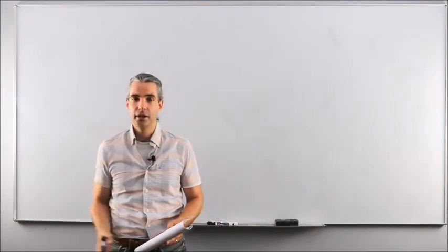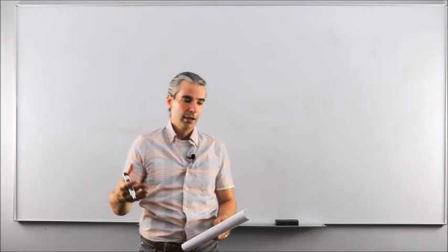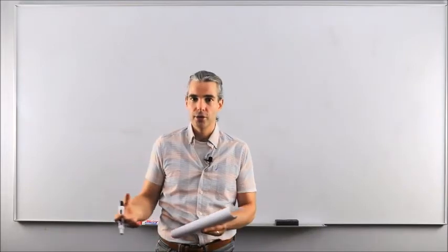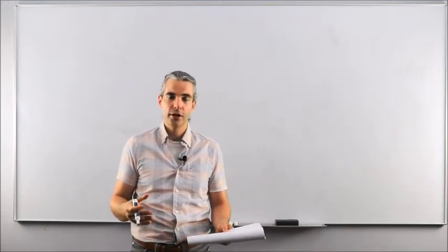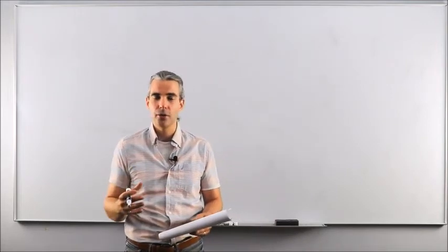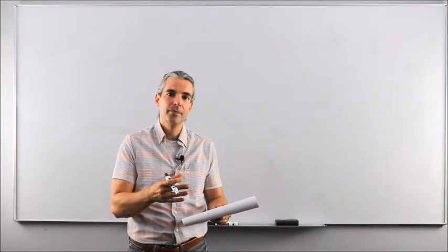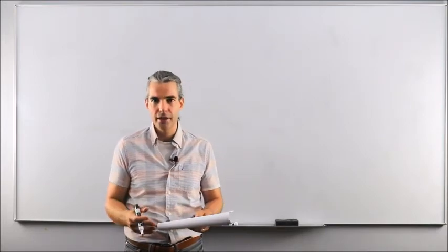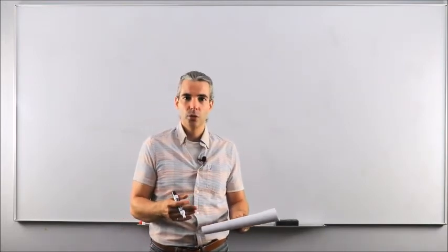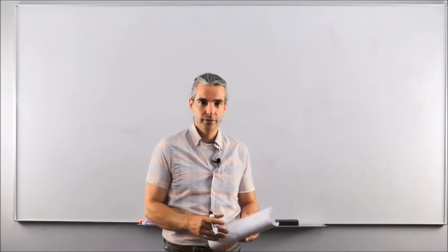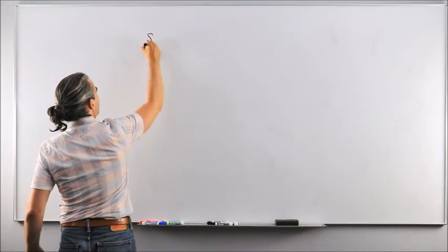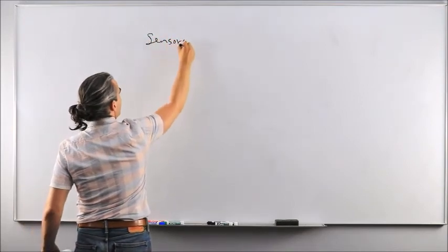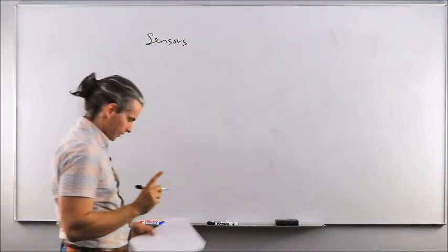So the command is 110 kilometers an hour, and the sensors are measuring a current speed of 100 kilometers an hour, and therefore there is an error of 10 kilometers an hour, and based on that, the onboard controller will do some math and say, okay, we need to accelerate by this amount. Okay?